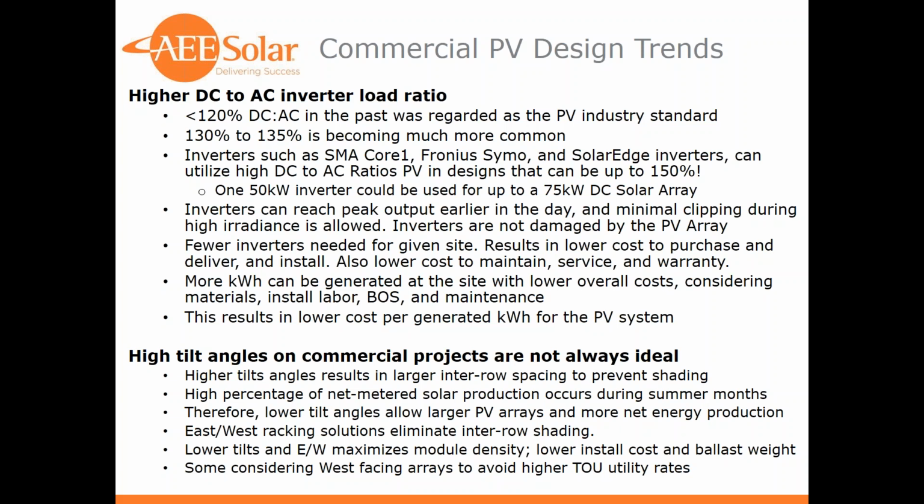And inverters are specifically advertising that they can achieve these higher ratios and be warranted for that and be consistent with the output. So SMA's Core 1, the Fronius Simo inverters, and SolarEdge inverters, they all can utilize pretty high DC to AC ratios, sometimes up to 150%.